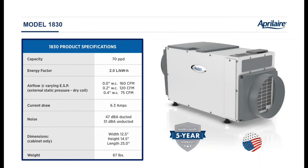We have spec sheets online at AprilAirePartners.com. I'm not going to go through all the specs. I just want to point out a couple things. We talked about the capacity. Look right below that, the energy factor: 2 liters per kilowatt hour. What does that mean? It means for every kilowatt hour of electricity we expend, we're going to remove a 2-liter bottle of water. Again, that's at 80 degrees Fahrenheit, 60% relative humidity.